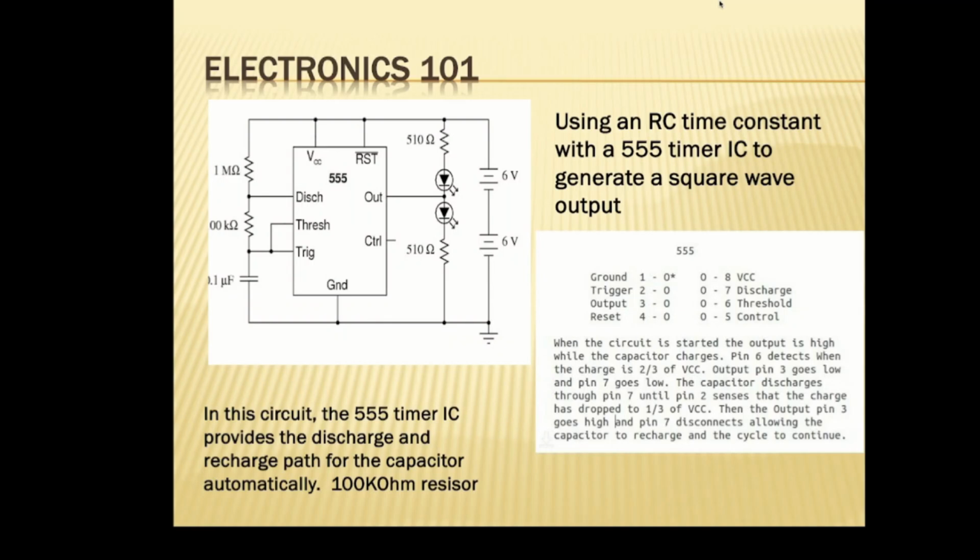And then the IC itself will cause a discharge, and it'll repeat over and over. And we put 2 LEDs on the output over here, and so we'll blink the LEDs back and forth at about a 1 second rate. But the blink rate of these 2 LEDs is controlled by these 2 values on that IC. That's a very practical application.